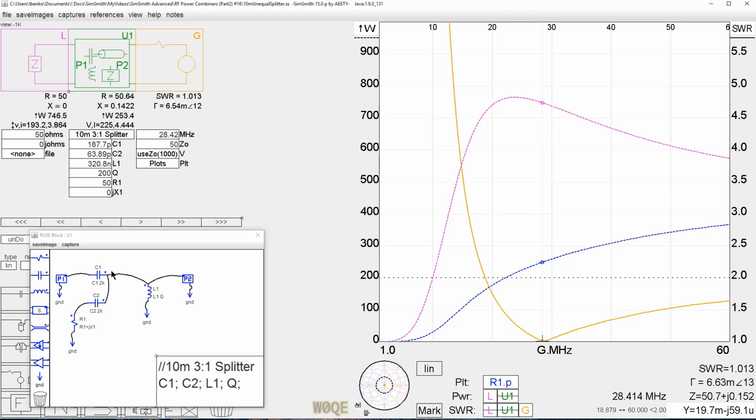Now, at this point, if we look at this circuit closely, everybody should recognize it. It's the high-pass T-tuner, which is kind of interesting. This point right here is either the input or the output to the tuner. This is the other one, the output or the input. This point normally is not connected. But if you had an old T-tuner at home and you drilled a hole in the back of it, mounted an extra connector right here and wired it to the junction between the two capacitors and the inductor, this would be this circuit.